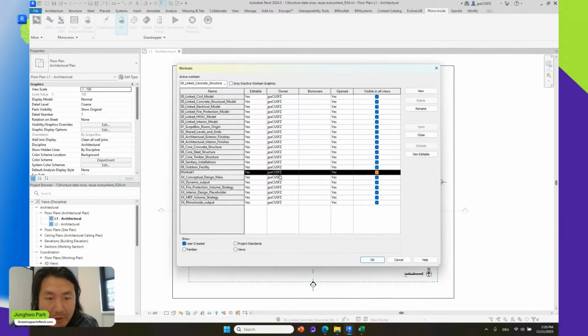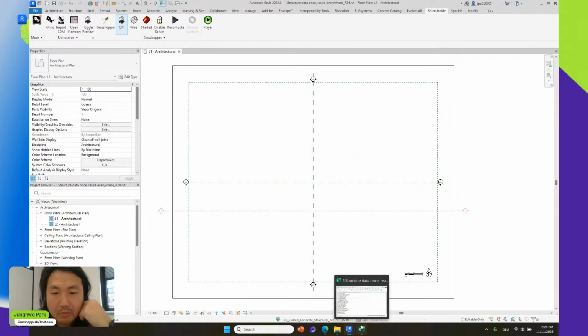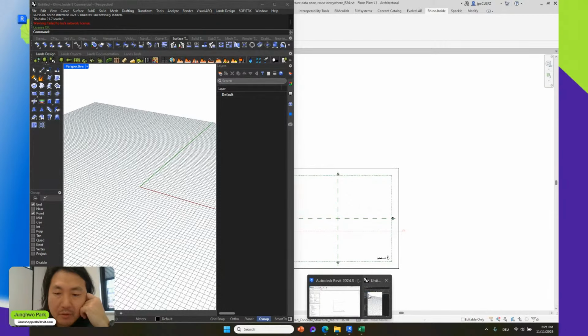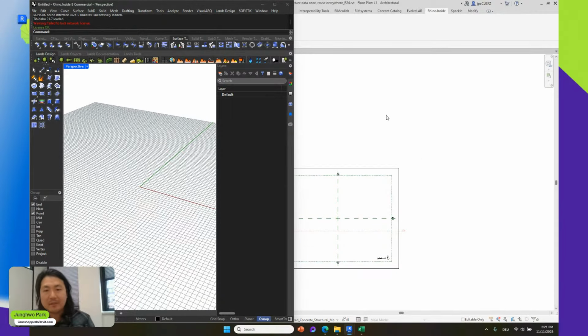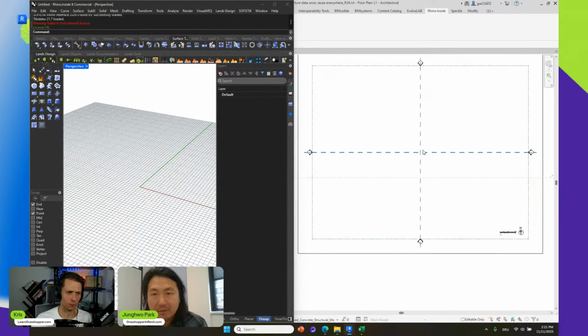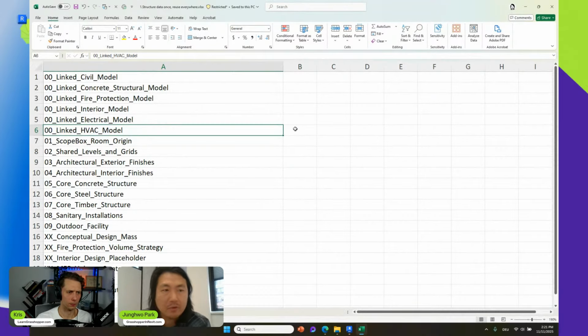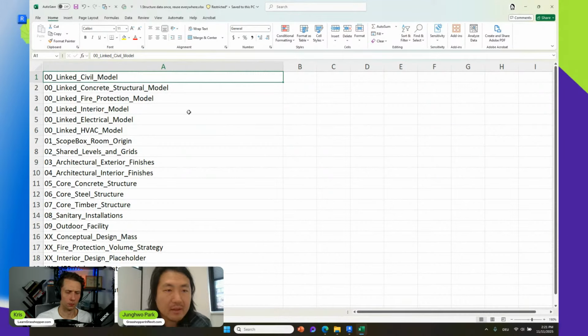Only one thing: that first initial default workset we cannot really delete, and that's the limitation, but you can rename it, or delete it manually and then move all the elements to a newly assigned workset. So this is my first content. I know some of you may be confused about worksets, but the power I want to demonstrate here is this data streaming from different Excel files, different data as an input, and then it automatically changes that information.